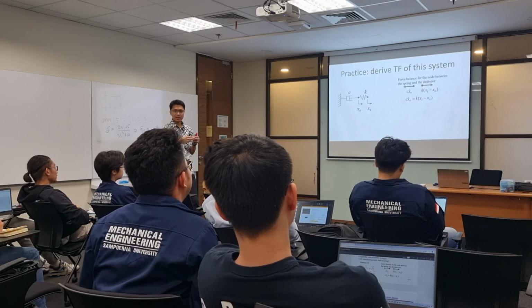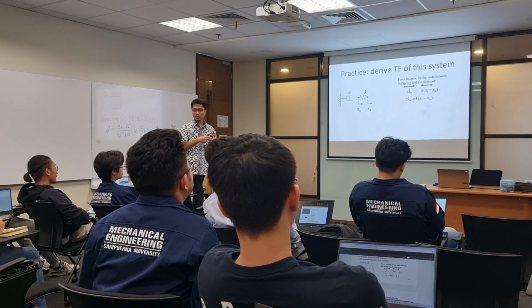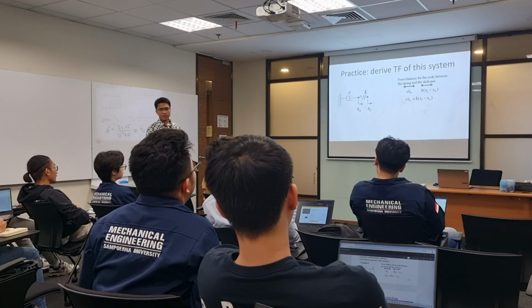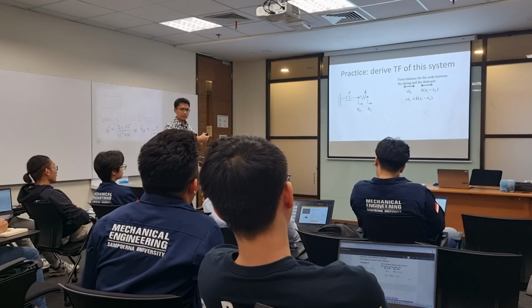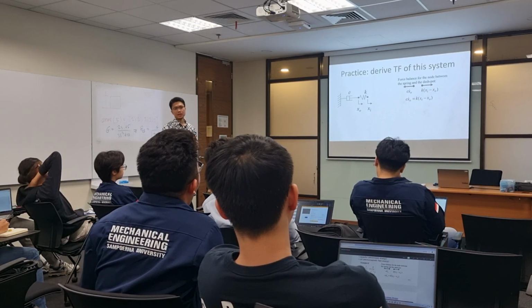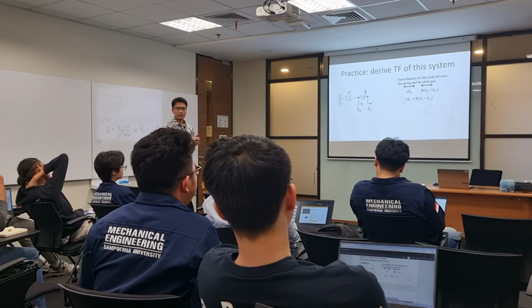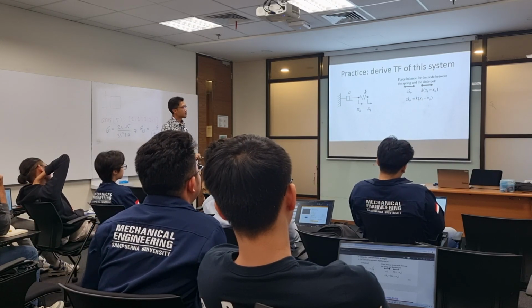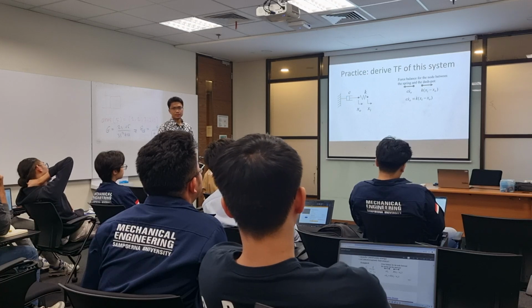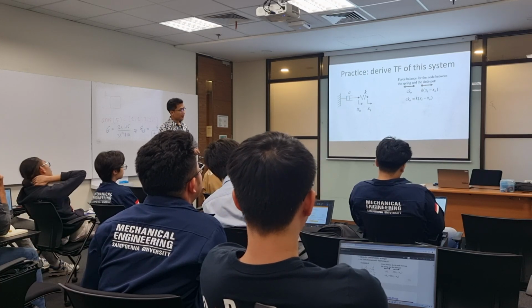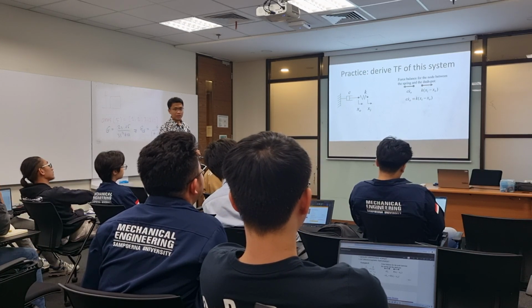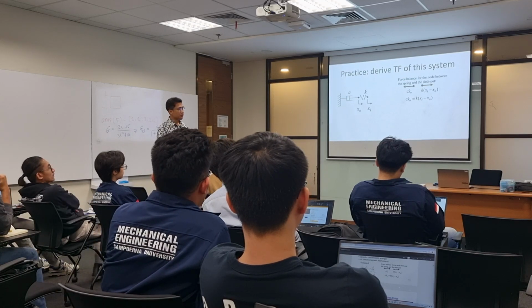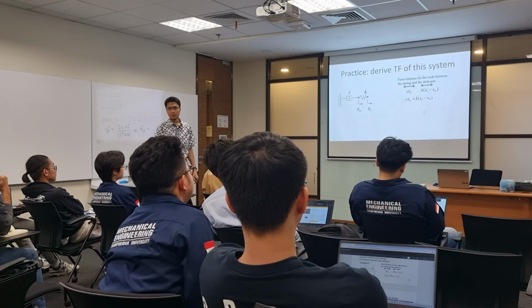It's how much the spring is being extended or compressed. If the spring is extended, then the force will be coming in. If the spring is compressed, the force will be coming out from the spring. So the force is assumed to be to the right, if we assume that xi is greater than x0.